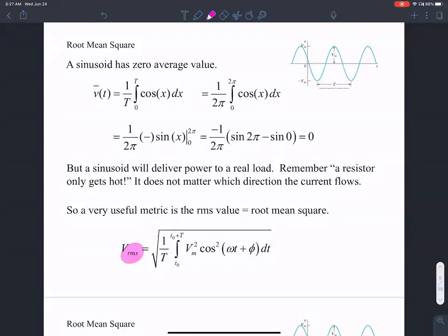to understand positive and negatively spread terms, we define root mean squared, where we square the wave of interest to me, or the input of interest to me, and add them. Find the sum of the squares, divide that by time, and then find the square root of that.